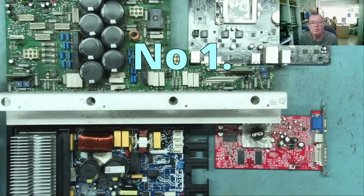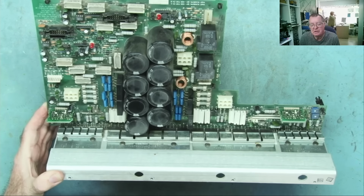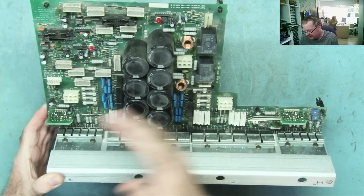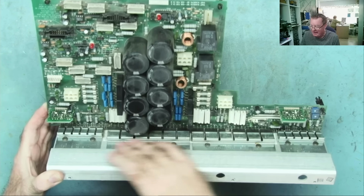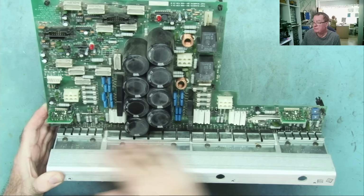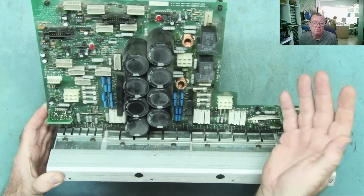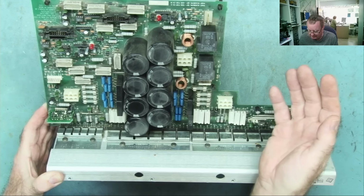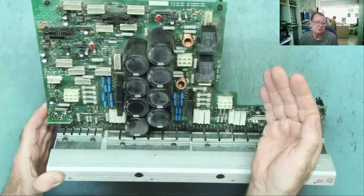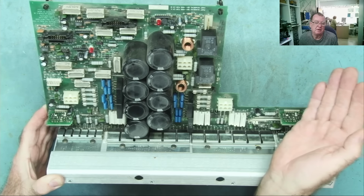So, number 1, power devices. Power devices are usually found on the output of a device. In the case of this amplifier, we have output transistors. That's these large things here. We also have some smaller transistors you can see. But power devices are not only transistors or MOSFETs. They can also be things like SCRs, thyristors, triacs. Anything that is driving some device.